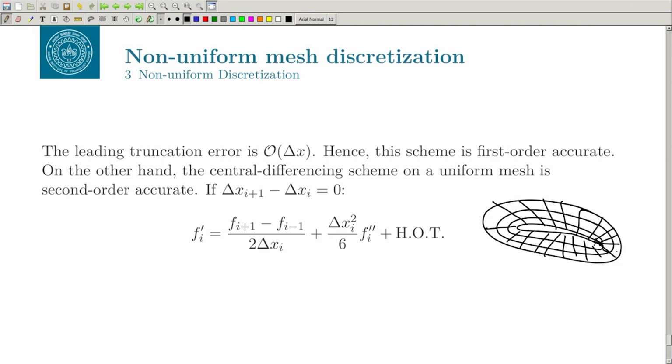All of the things that we have discussed are for the uniform mesh, on a Cartesian system, let us say x, y or x, y and z, where things are changing very smoothly and uniformly. But we can use those formulations and all those ideas on a non-uniform mesh, or even a mesh like this, by doing something called curvilinear transformation.